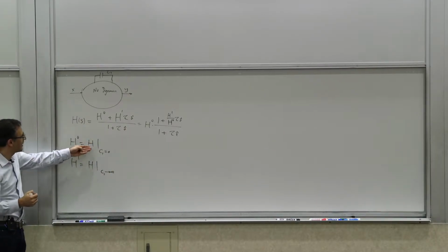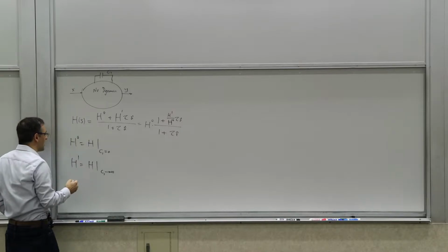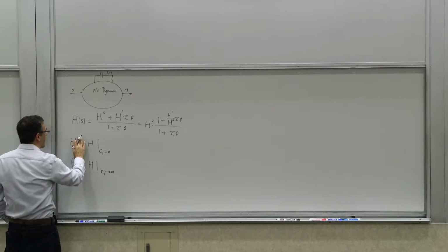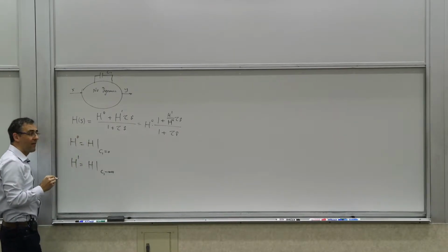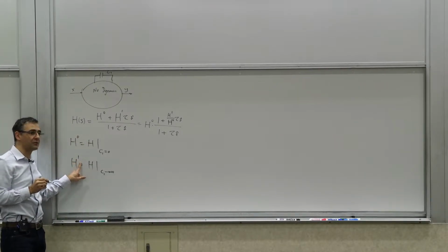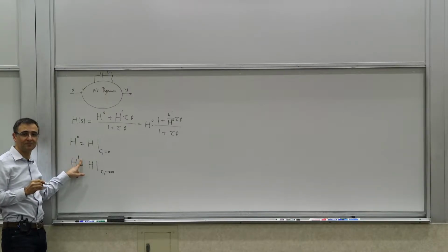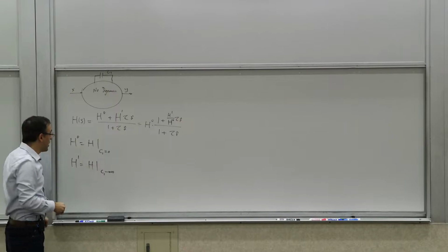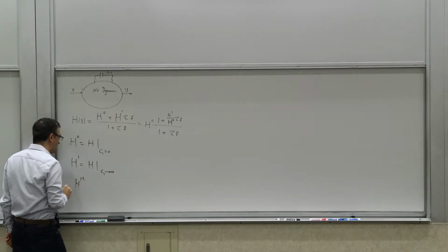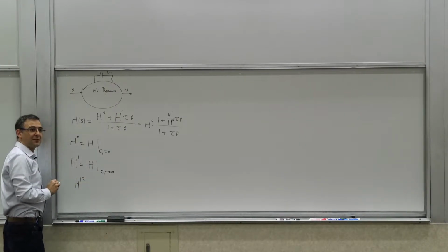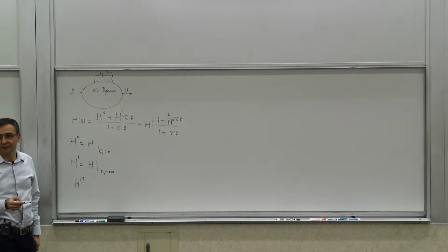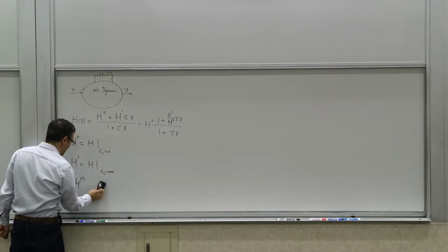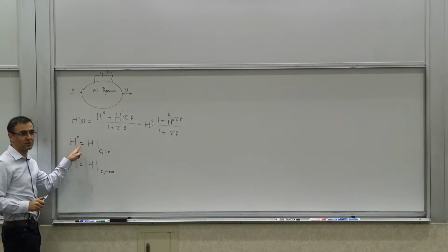If it was an L, it would be 0 valued and infinite valued too. In these superscripts, in general, are the indices of the elements that are infinite valued. So if it says H superscript 1, it means that element 1 is infinite valued. Later on, if you have H superscript 1,2, it means that elements 1 and 2 are infinite valued. So get familiar with that notation. And if the superscript is 0, it means that nothing is infinite valued.